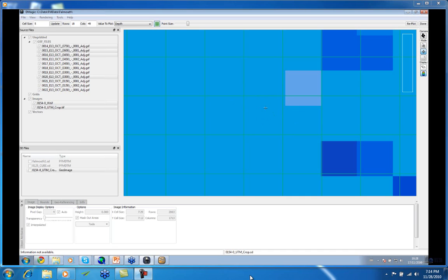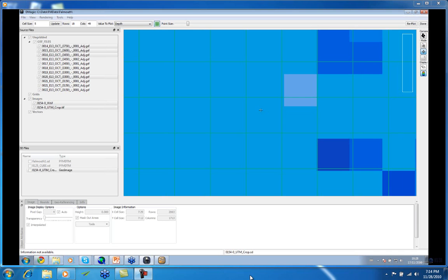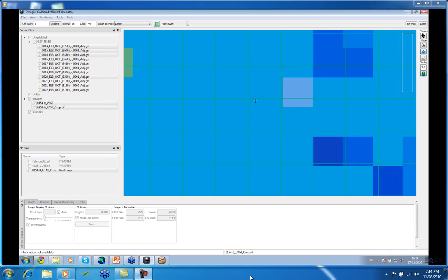So the Cube way of gridding, if you like, is more correct, but the weighted moving average is also quite a good way of just gridding the data. A weight diameter of 5 would take in a 5 by 5 cell, which is generally too much, and you end up smoothing the data. So 3 by 3 is the default for a weighted moving average, and that's the weight diameter of 3, which is 3 by 3 cells.